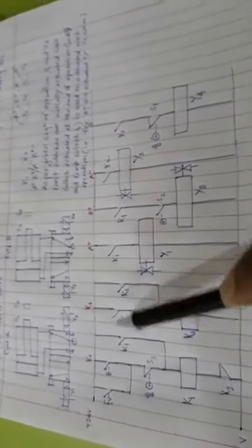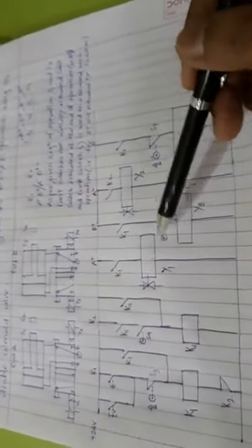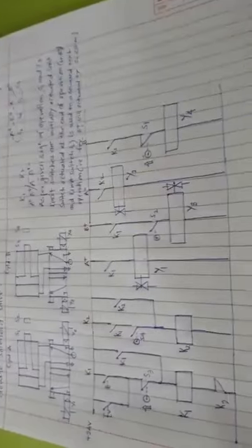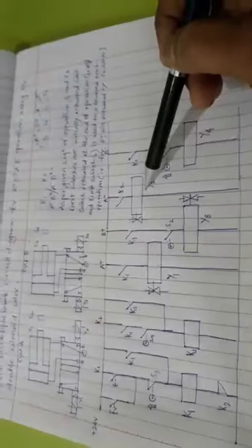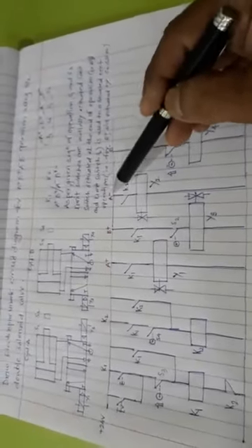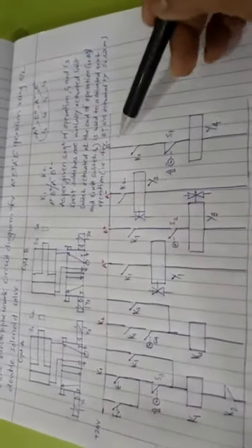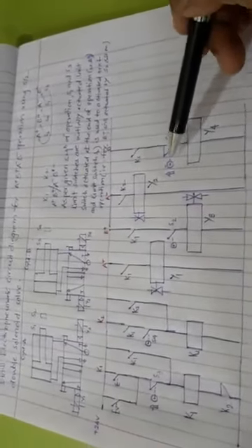As it will be open, K1 will be de-energized, it will be off. As it will be off, the contacts related with K1 which were closed will be open, and Y1 and Y3 will be de-energized. In this way, K2 will be closed, Y2 will be energized, and the A minus operation will be completed, and it touches S1, which is initially actuated.